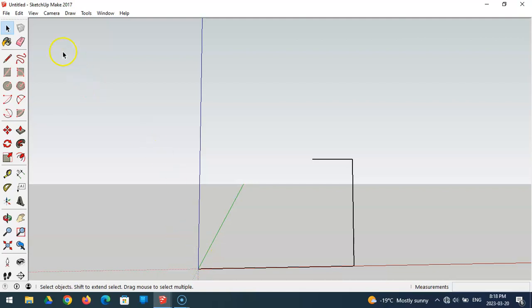Now let's draw from here. So go grab the pencil tool and click on the origin, drop the line on the blue, and type in 125, and press enter. And now we're going to go to the right on the red, let go of the mouse, type in 50, and press enter. I'm still attached, so let's press escape. Now what a great time to save it.